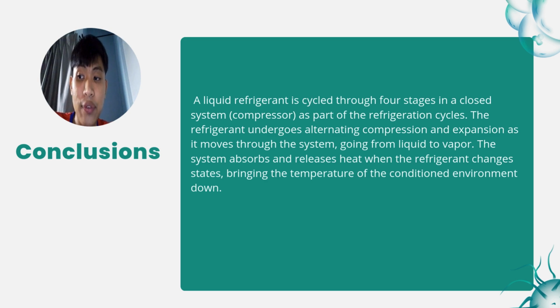So from the experiment itself, we have achieved the objective of the experiment because we have increased the load. All components of the refrigeration cycle were affected. The parameters such as pressure, enthalpy, and temperature at the four states of the refrigeration cycle were determined and calculated. This enabled us to calculate the COP, as I mentioned just now, and the efficiency of the refrigeration cycle. As discussed before, I think that's all from me.